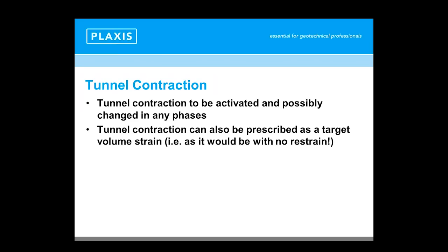So it's a slightly different method, but you can also apply a volume contraction into the soil mass, which is supposed to be removed, and leading also to tunnel contraction, should you be willing to investigate the effects on subsurface subsidence or stress redistribution to the existing buildings.